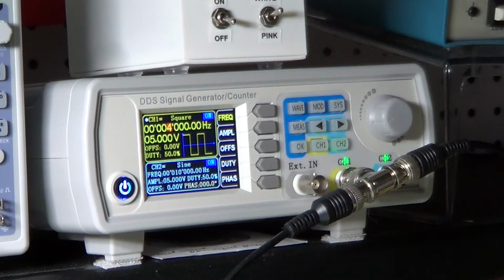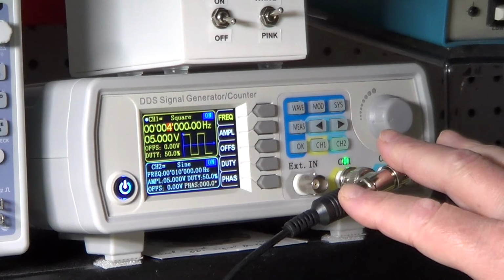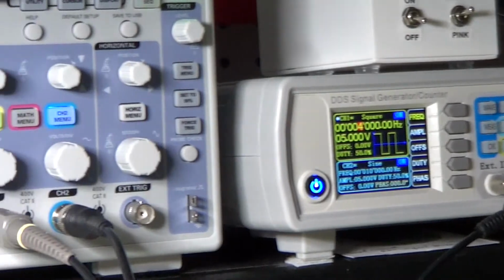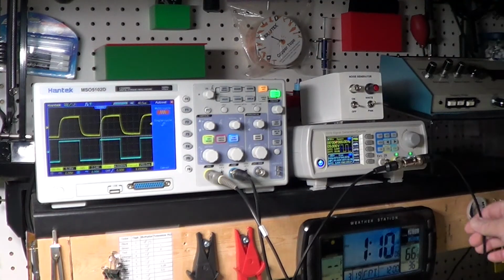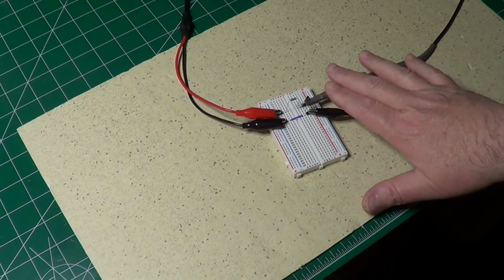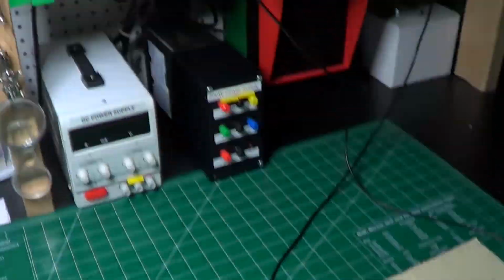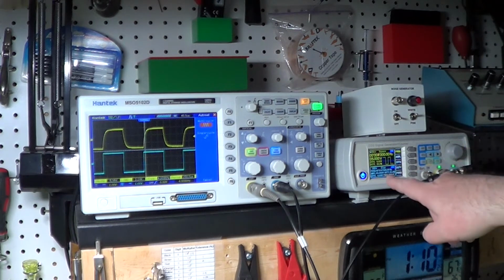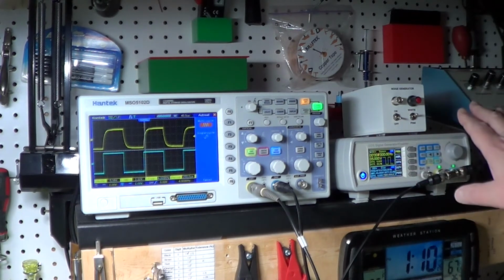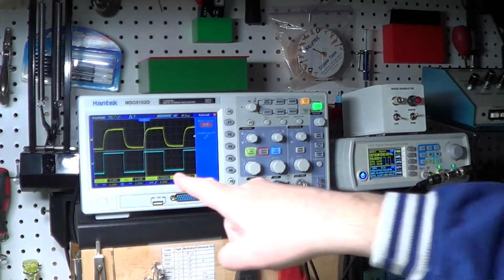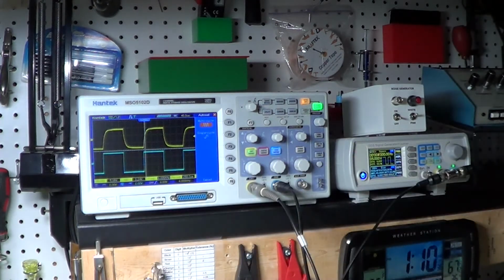Let's do it. For this other experiment, I reconnected the cables in such a way that the output of the function generator will go to the oscilloscope, right here, and the other end will go directly to the input of the filter that we are testing, and instead the other goes directly to the oscilloscope itself. So here is what we are seeing right now. I have generated this time a frequency of 4 kHz, but instead of using a sine wave, I'm using a square wave, again with the amplitude of 5 volts. This is a square wave to the input of the filter, but look what the output looks like.